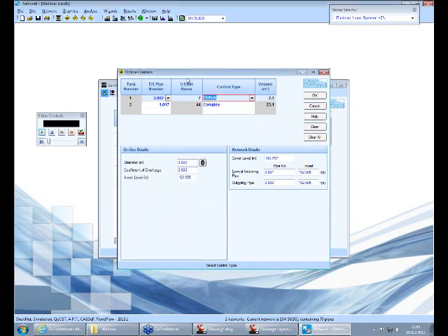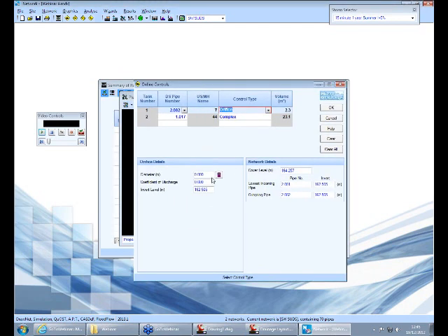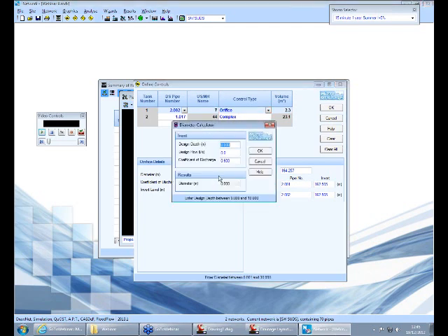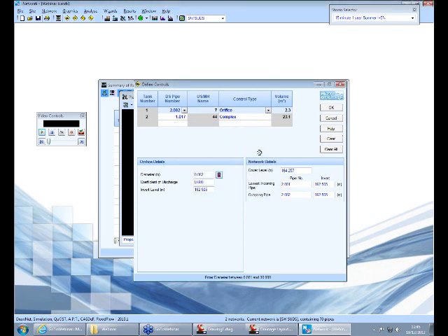So for example, on this storage structure, if we wanted to limit the flow from the storage structure so we were able to maximize the amount of water held back and fill the storage structure to its capacity, we could have an orifice with a design head of say 1.5 and an outflow of 10 liters per second. The downside of using an orifice is you end up with a diameter less than 100 millimeters, so it may not be adoptable by some authorities.